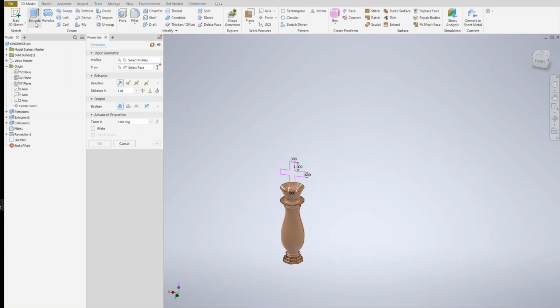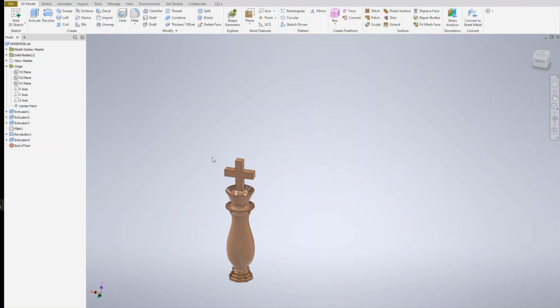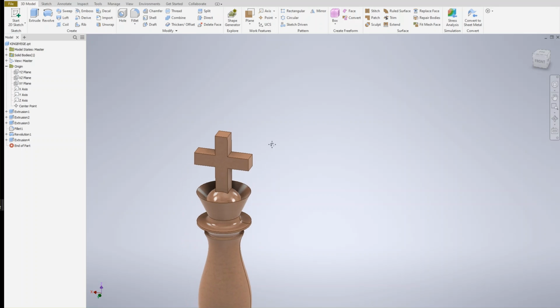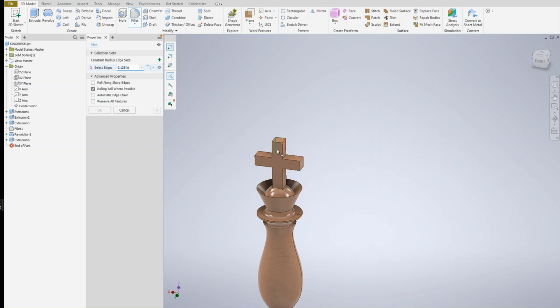And let's use the extrude command. It should be a two-way extrusion. Okay. And select the area. 1 inch is too much, and 0.6 is probably far better. Okay. And okay. And there are a number of things you can do. You can just add a fillet, for example, to the corners. Fillet is about a 0.1 inch fillet. Would that work?